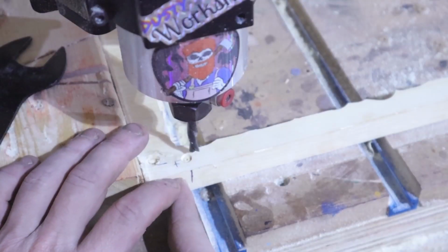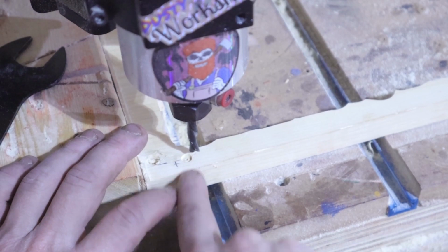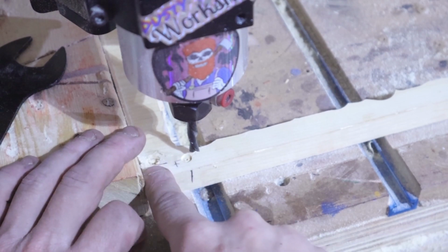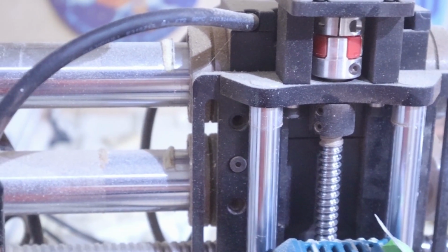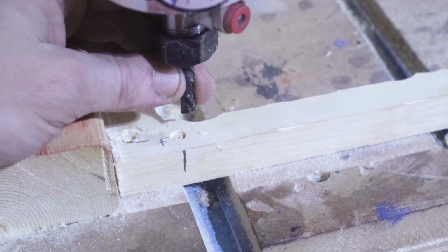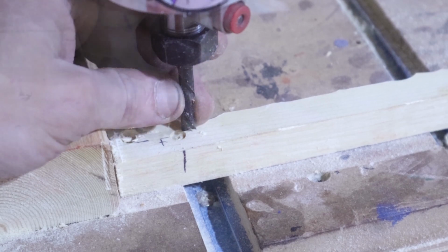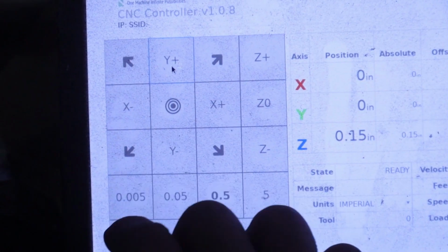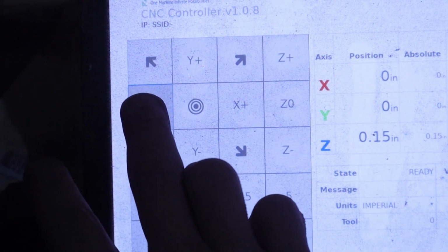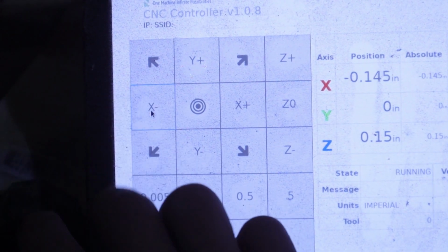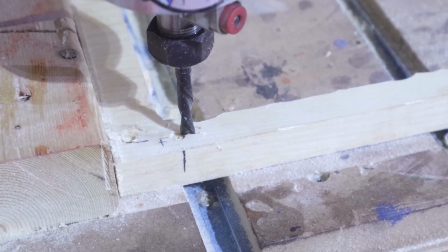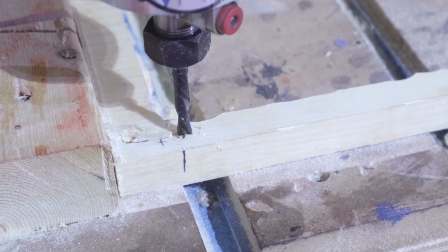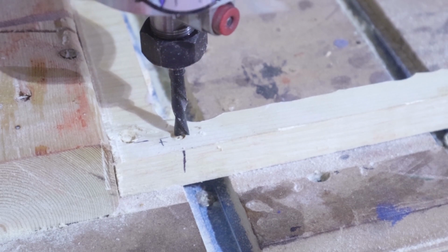So if you ever come across this problem, the first step is, when you first start your project, I usually mark out my datum. Once you set your XY home for a project on your CNC, turn on your router, then manually slowly plunge, just so you have a saved reference point, just in case. Given in this instance Y never moved, it was only my X, all I would have to do is slide my X position over while I have the corresponding bit that I used loosely inside the collet. Once the bit drops, you know you have found your X or Y. Just keep in mind it's not the be-all-end-all tip, but it should bring you back to what you had.